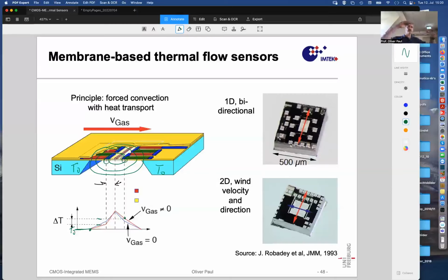Now you have two thermopiles which provide an output signal, and the difference of those output signals is what you want to measure. So what you do is you put those two thermopiles in series, or rather in anti-series. You subtract one of the voltages from the other.